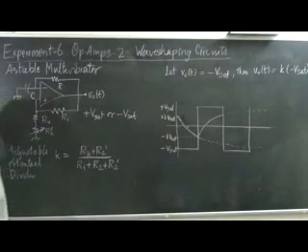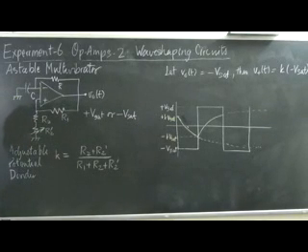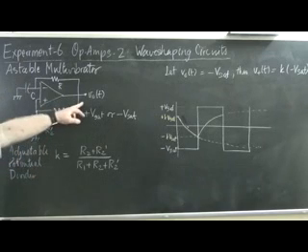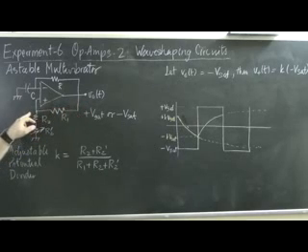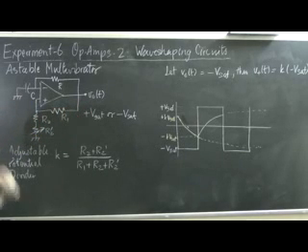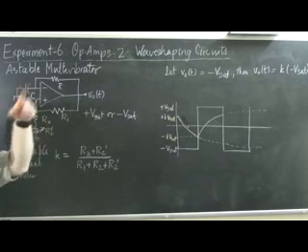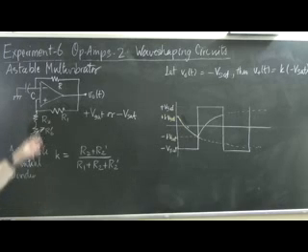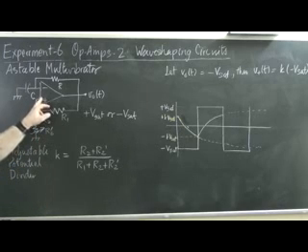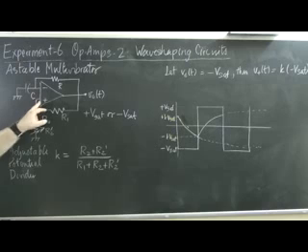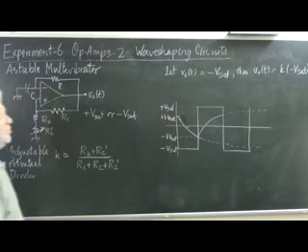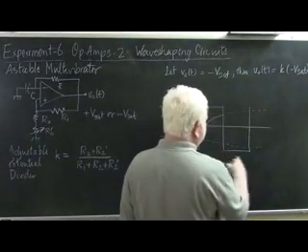With an intention to eventually become equal to plus Vsat. Again, as soon as the output switched to plus Vsat, we have plus k Vsat at the non-inverting terminal, and the capacitor voltage rises towards plus Vsat, but at the moment that it crosses plus k Vsat, the inverting terminal voltage has now again exceeded the non-inverting terminal voltage and caused the output to switch to minus Vsat.